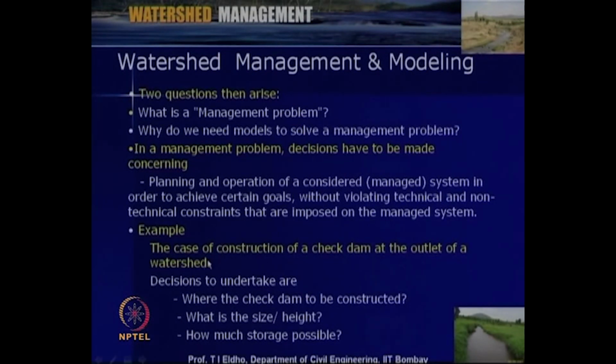Say for example, the case of construction of a check dam at the outlet of a watershed. If this is the outlet of the watershed and we are planning to construct a check dam, we should know what the size of the check dam should be, where the check dam is to be constructed, what the height is, and how much storage is possible. So, for all of this we have to rely upon modeling, since it is a very complex process, since we are dealing with nature.